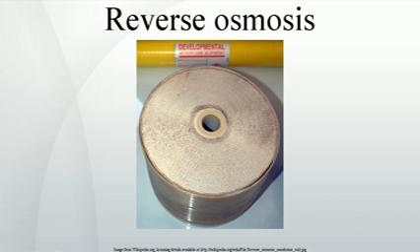The clarified water is then fed through a high-pressure piston pump into a series of vessels where it is subject to reverse osmosis. The product water is free of 90.00 to 99.98% of the raw water's total dissolved solids and by military standards, should have no more than 1,000 to 1,500 parts per million by measure of electrical conductivity. It is then disinfected with chlorine and stored for later use.